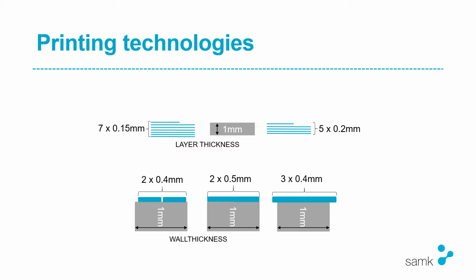So it does have to compensate with one of the layers or a few of the layers to get that 1 millimeter of thickness to the part. But then again, if we use 0.2 millimeter layers for that 1 millimeter, we get an even result and it adds up a bit better. So if possible, the layer thicknesses should be taken into consideration when 3D modeling. You don't have to, but if it's possible, it should be used because it helps with the quality a bit.